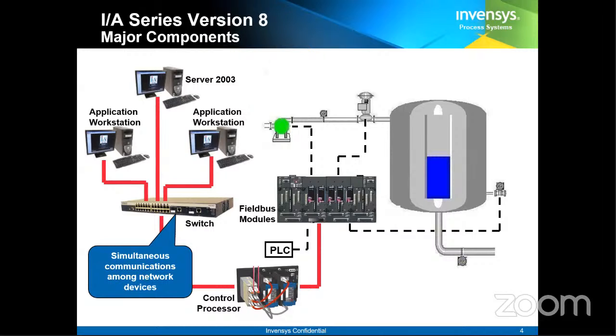You will not be able to go everywhere to see what is happening in this area, inside the boiler, inside the turbine room, or in the chiller. So you need to sit at one place, which you call a control room, and from there you want to see everything. Your DCS system will fulfill that.